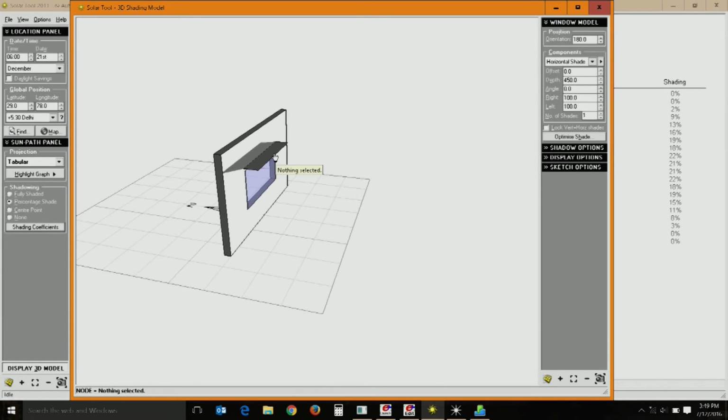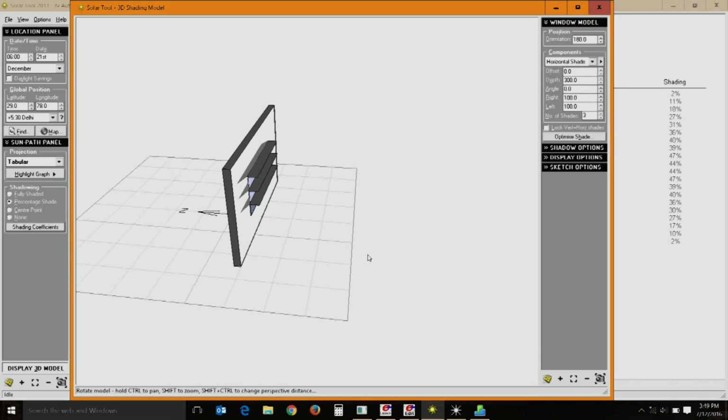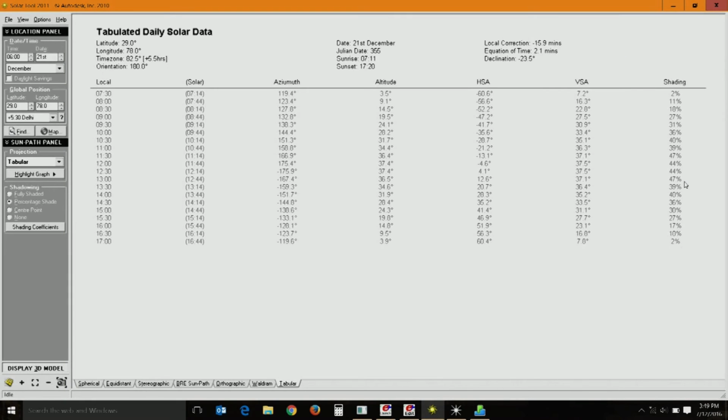This shading device is there. If you want to increase the number of shading devices, now we have a horizontal shading device, make it 2 horizontal, it evenly spreads out, want to make it 3, instead of 450 mm, say let us go for a 300 mm shading device, a thin one, but I can go for 3 numbers. We will go back and see what we have got.